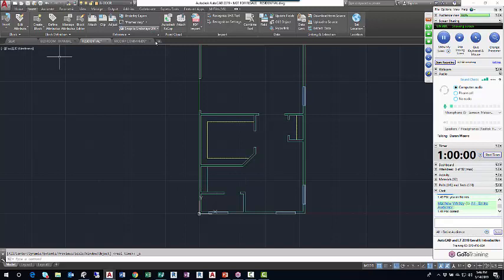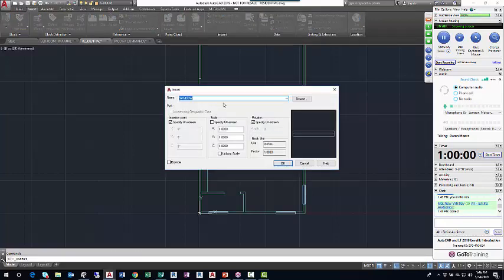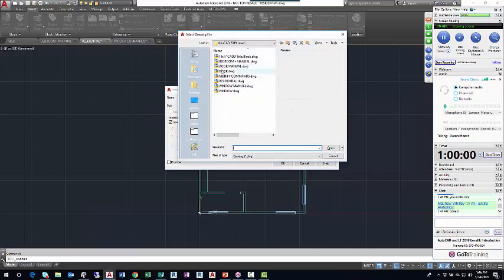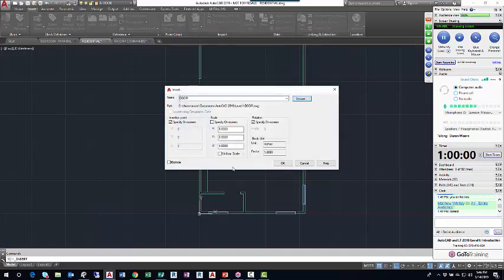So anyways, A door is architectural door, and I'm going to use that layer and I'm going to bring in a different block, right? So if I click insert, I'm getting the block gallery. I'm seeing the window, but I want the door. So I'll click more options. I'm in my insert dialog box. I'll browse, click door, click open, and then I'll click OK.